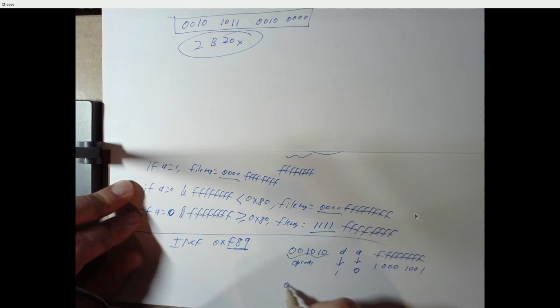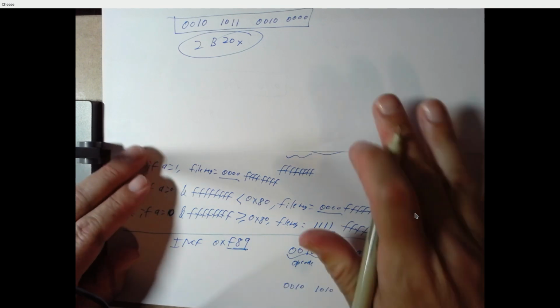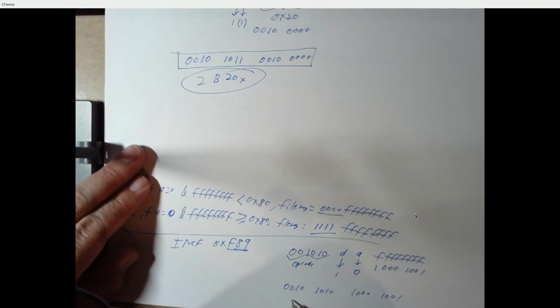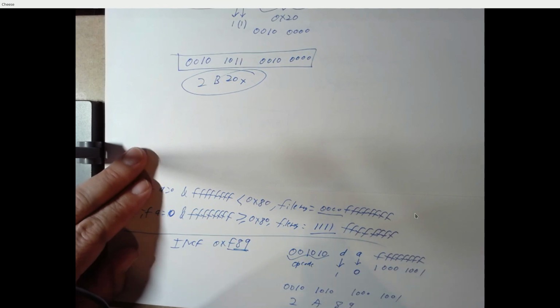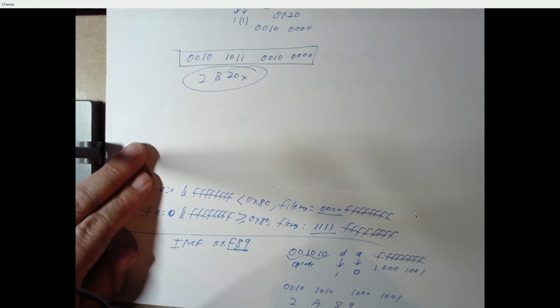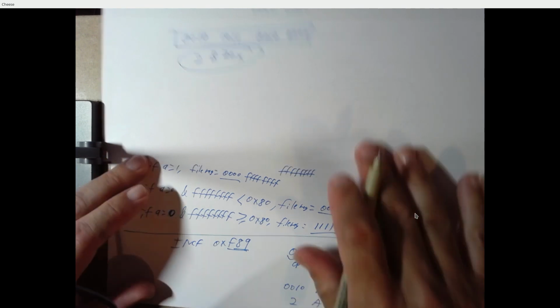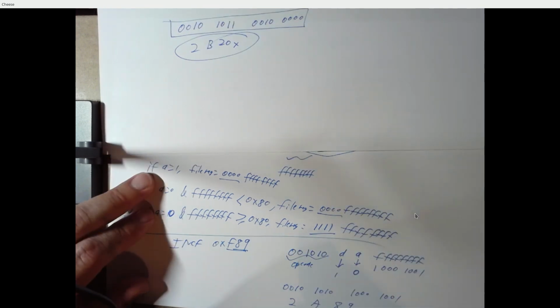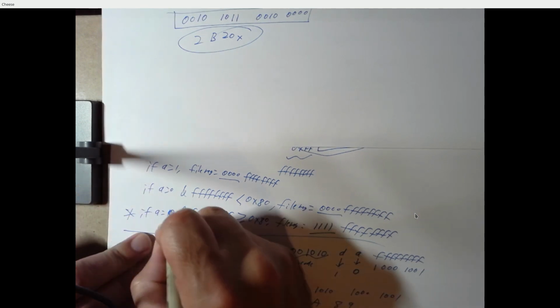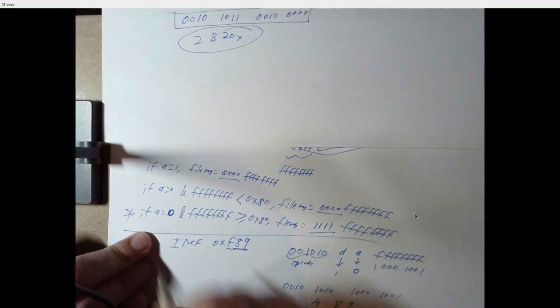So this instruction 0010, 1010, 1000, 1001, or if we were to write it in hex, this is 2, this is A, this is 8, this is 9, right? This instruction says increment file register F89. If we made the access bit a 1, this would increment file register 089. So the access bit, and I'm sorry, this is a 0, not a 1. I made a mistake before.